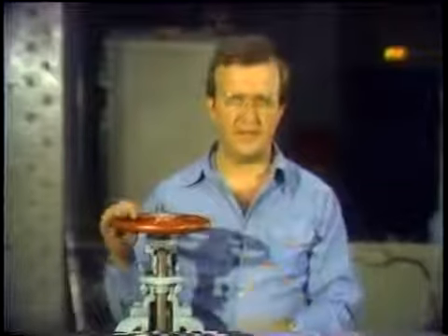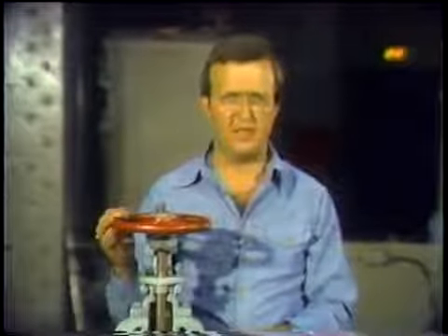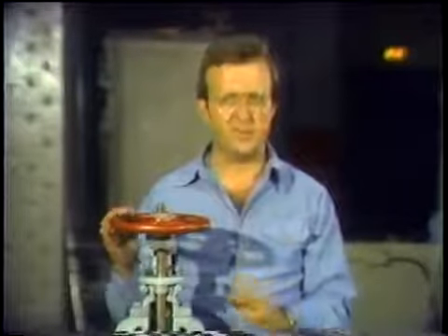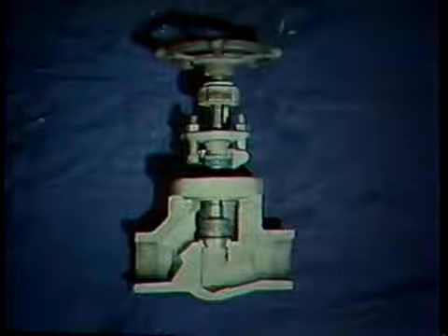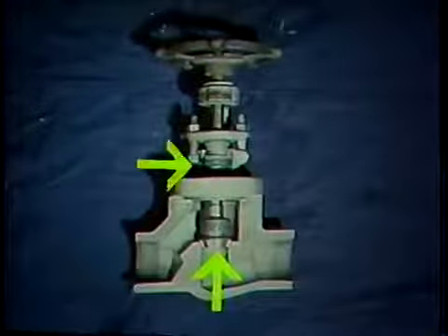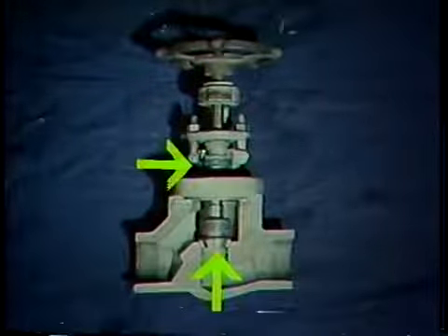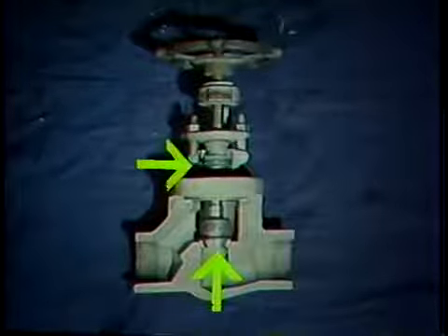Anytime you replace a valve in a system, you must be sure that the replacement valve meets the same specifications as the original valve. It must be installed to allow proper flow from the system through the valve and out again. Normally, a valve is installed so that the high pressure from the fluid or gas is under the disc when the valve is closed. In that way, there will be no pressure on the valve packing, and this reduces the danger of leakage at the place where the stem goes through the bonnet.